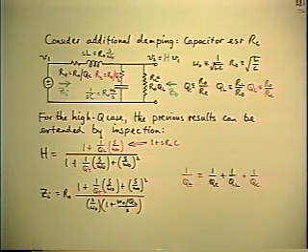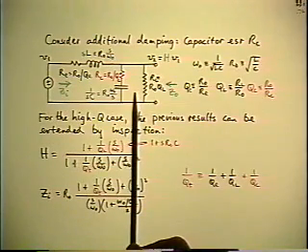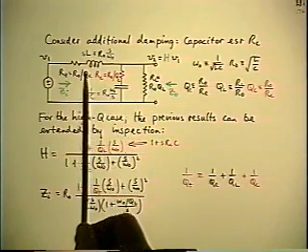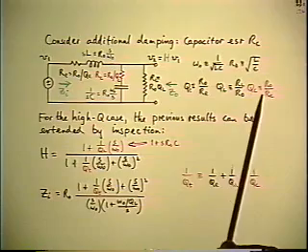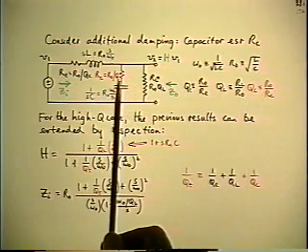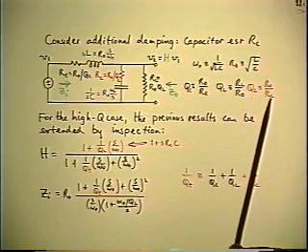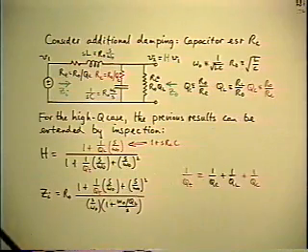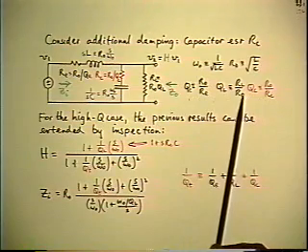So now, following the same procedure, if we want to know the three functions, voltage transfer, input and output impedance, for the case of the LC filter with three sources of damping, first thing is, again, introduce the normalizing quantities right from the start and define a third Q factor corresponding to the added resistor. So now we want a QC related to the RC. So we have the choice now of which way up shall we define it. Shall we define it like the QE or like the QL?